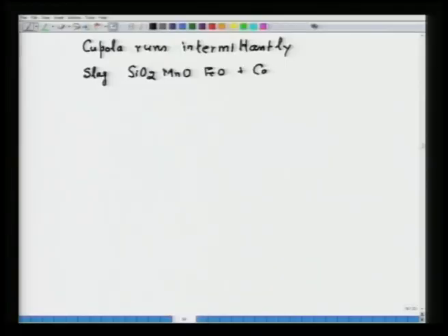So, that calcium oxide helps to form the slag and slags off all the impurities. It may sometimes contain some amount of calcium oxide. So, that is in short the operation of the cupola. Now, the further operation I will illustrate through problems on material balance in the cupola. So, let me go to the material balance in the cupola.